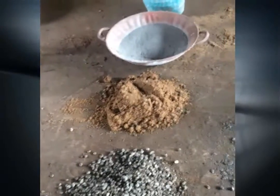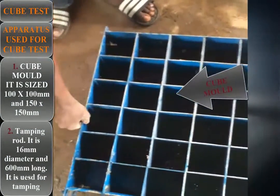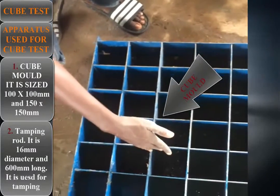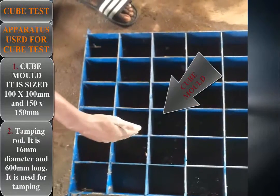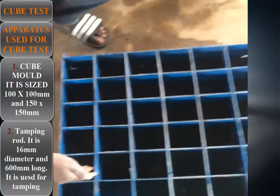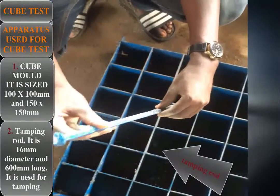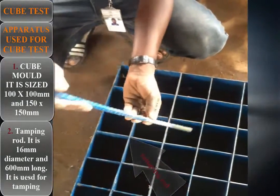Apparatus for cube tests. The following apparatus are used for cube tests. One, the cube mold. As you can see, this is the cube mold that is 100 by 100 millimeter in size. We have that of 150 by 150 millimeter size. Two, the second apparatus is the tamping rod. This is 16 millimeter in diameter and 600 millimeter long. It is used for tamping.